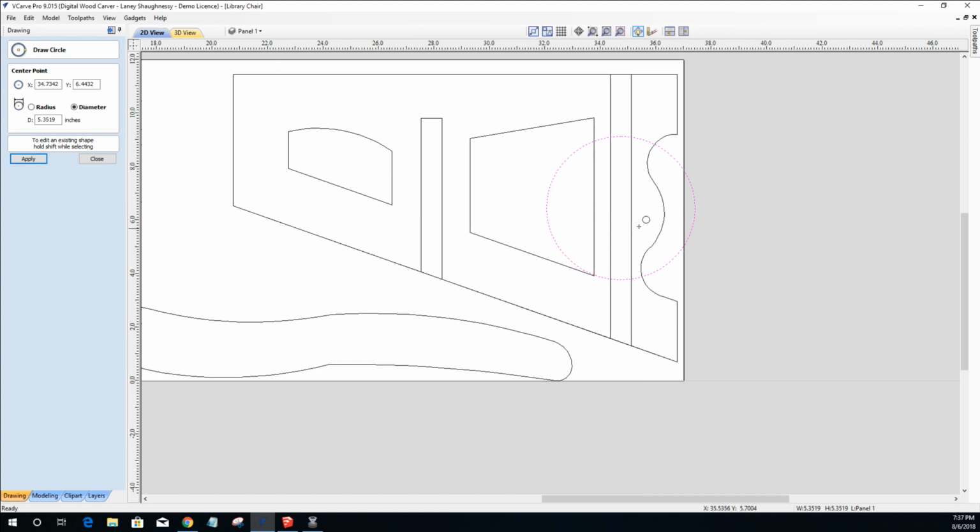It's running in a vertical pattern, and if any part of this chair is going to be a weak point, this area in here is going to be the weakest, and the last thing you want is the chair to break under somebody. So this 1/4 inch deep, 3/4 inch wide spline is a good way of reinforcing that area.